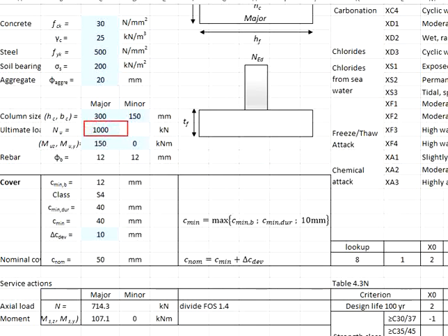With the given ultimate limit state loading, we don't know how much is contributed by the Gk and how much from the Qk. You know the factor of safety for Gk is 1.35 and for Qk is 1.5. Not knowing the quantum of the Gk and the Qk, we cannot use the factors of 1.35 and 1.5 directly. Therefore, we will need to estimate the service load by dividing the ultimate load with the factor of safety of 1.4.